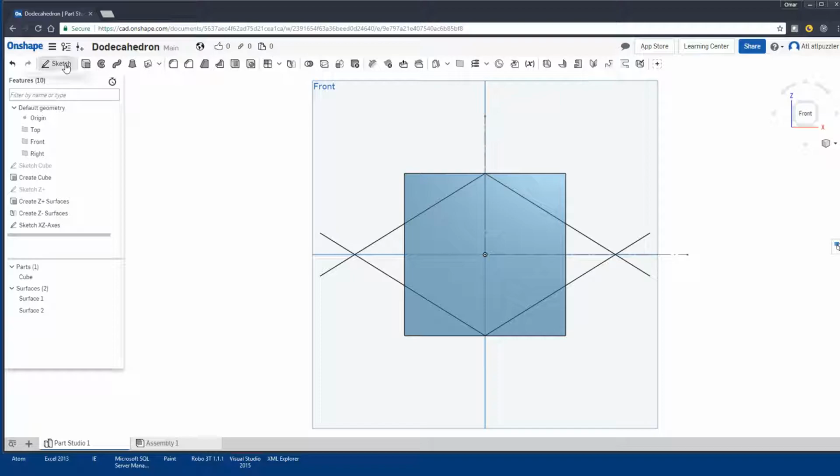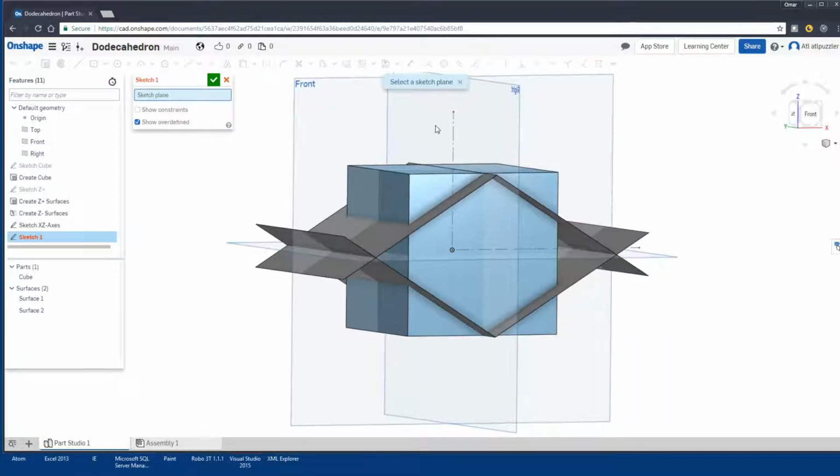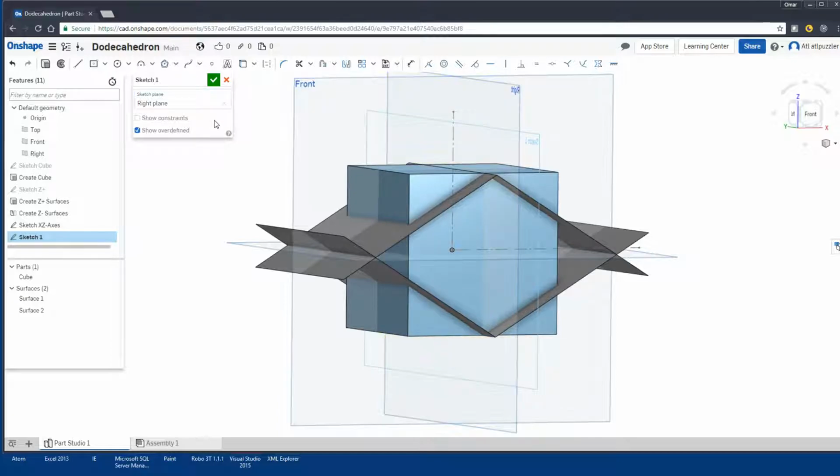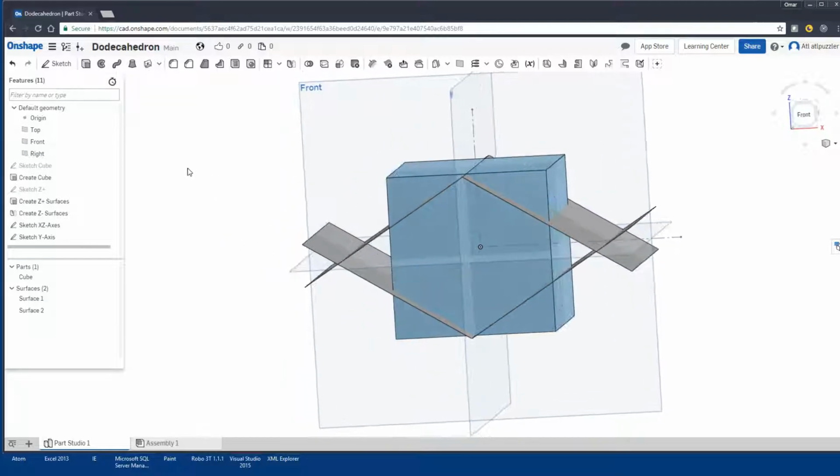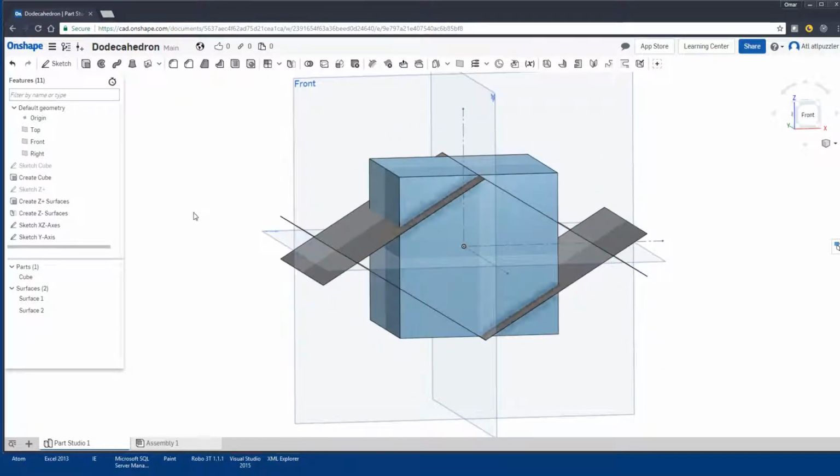And let's make another sketch, but this time on the right plane, and make a construction line from the origin. Make sure it's horizontal, and that will be the y-axis, I'm sorry, and do OK. Alright, so I hope this makes sense. These are just simple axes, and we can create a feature script for that if you guys like, and we'll talk about those in a moment.